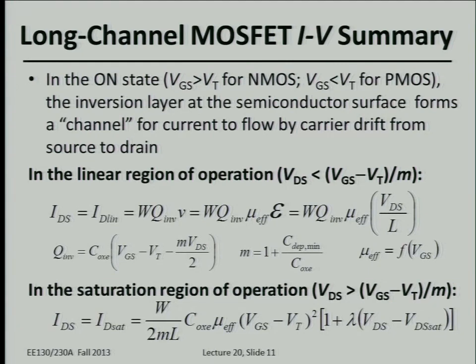What about this? How would you choose VT? Right, so low VT. Ideally, low threshold voltage means higher drive current, higher saturation current, so higher speed circuits. Very good. So in the design project, which is actually now posted online on the class website, I think the EE130 undergrad students will be asked to design something that has a relatively low VT.